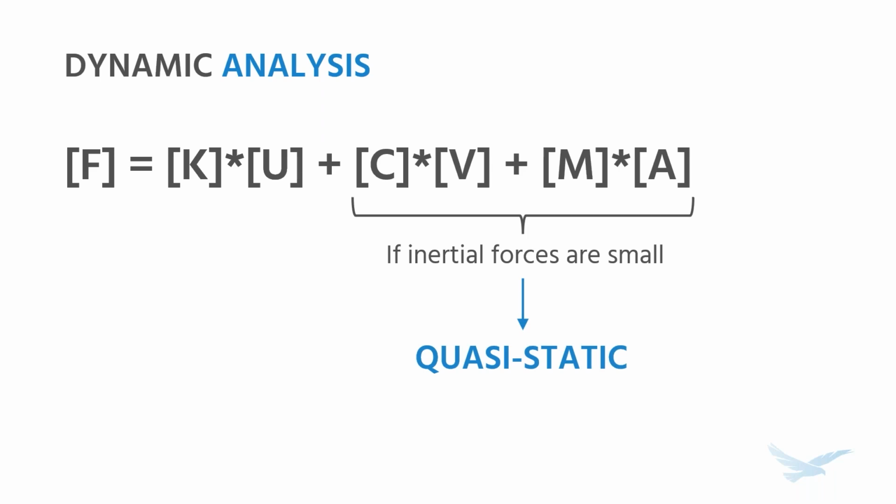We're using these extra terms to help balance the equations so that we can either solve the problem if it wasn't solving before, or maybe we can solve it a little more quickly with larger time steps. And while we aren't keeping those two inertial terms truly zero like they would be in a pure static analysis, if we're keeping them small enough, we'll still have a good result that can give us good information, allow us to make good decisions.